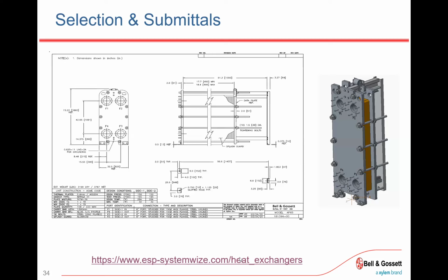And then this is really the sheet that everybody's looking for. That's your performance sheet, list of certifications, has some dimensions, plate count. Now, if somebody has an existing heat exchanger and you want to find this sheet for their heat exchanger, all we need is their serial number, and we can go back and log it, and then you can get this. You'll know everything from the flow rate to the plate thickness and the plate pattern. So if you wanted to say, what can I do with this unit? You can go into that rating portion, put these details in, change your conditions and see what's achievable.